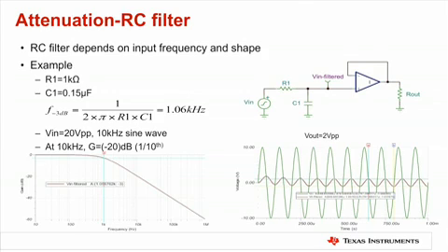To confirm the RC filter in the time domain, it's convenient to run transient analysis on a 10 kilohertz sinusoid that should be attenuated by 20 dB, or exactly 1/10. As you can see in this slide, the TINA-TI simulation confirms our expectations. The transients we need to protect our circuit from aren't perfect sinusoids though. They're closer to impulse signals.